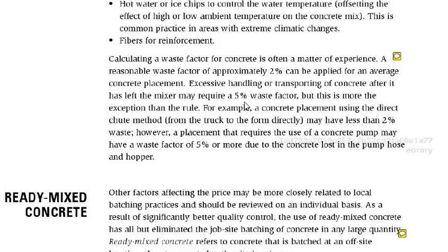But I hate to see this much. I generally don't see this much concrete. A good concrete crew doesn't waste concrete. Remember to put extra in for wastage. And when you do that in your calculations, you should indicate which percentage you're using, and then mark it as a wastage calculation and the total amount of cubic yards that you need.